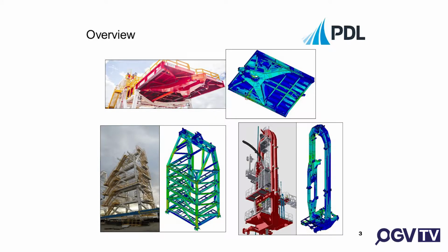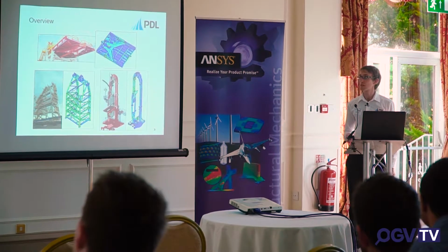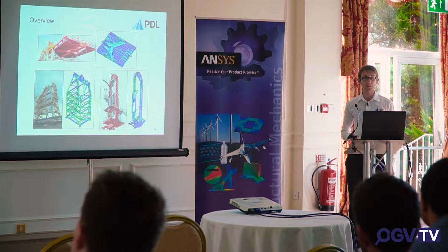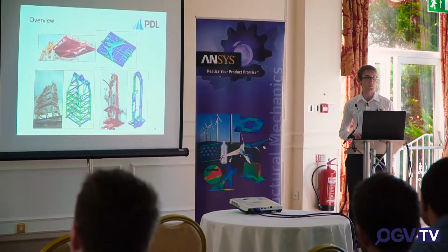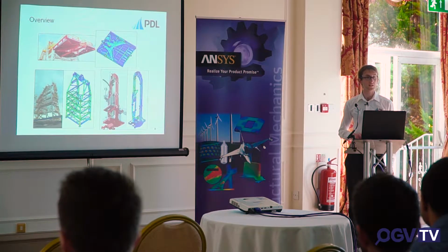So I just wanted to show you some images to start off with. All of these structures are mounted on ships. The top image is showing a sliding deck, or Mobo deck is its nickname because it holds a Mobo type pump. Basically it's in the middle of a ship and there's a moon pool, and the bit in red extends, slides over the moon pool. It can be used to support part of a riser. When not in use, it retracts out of the way.